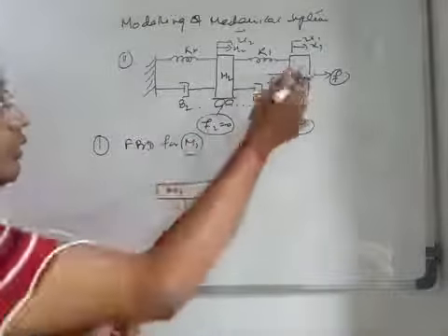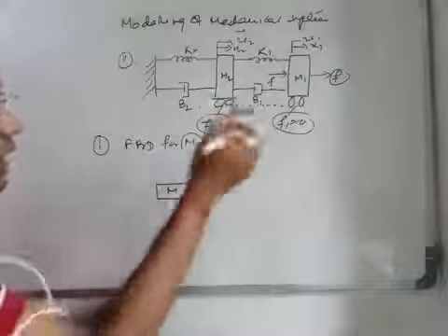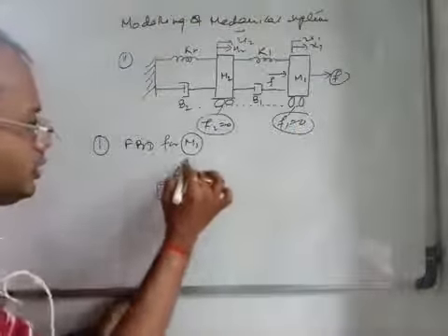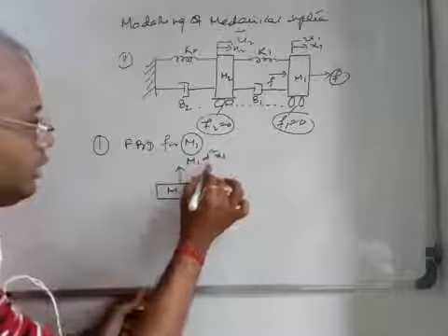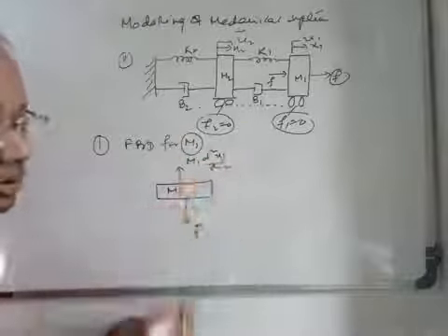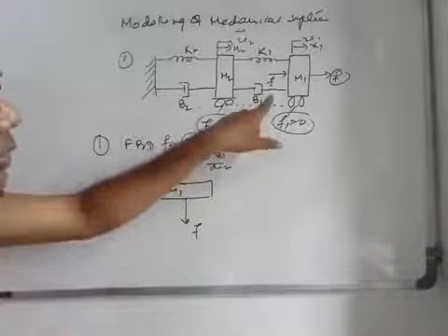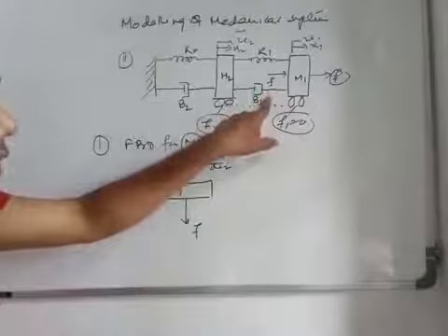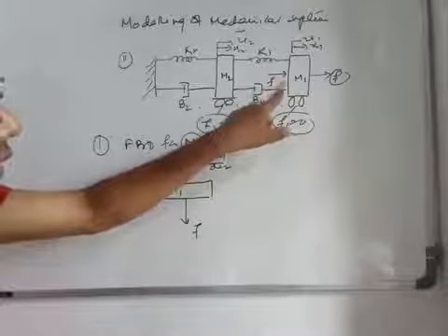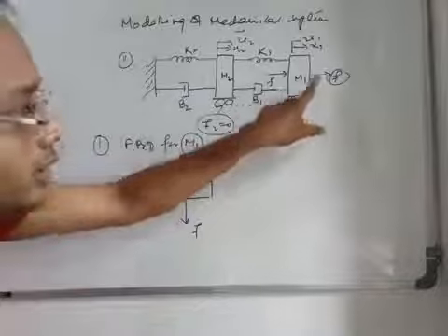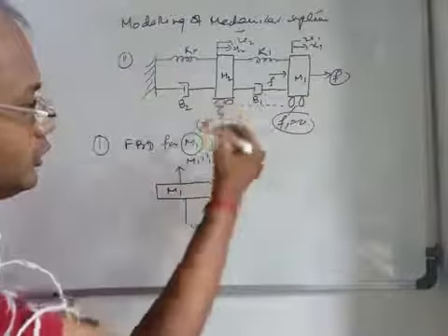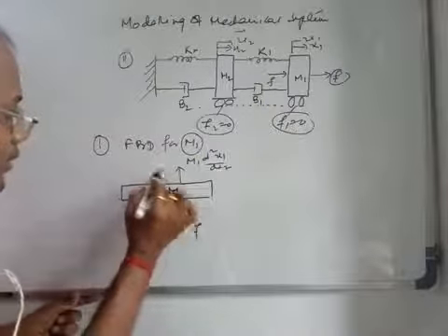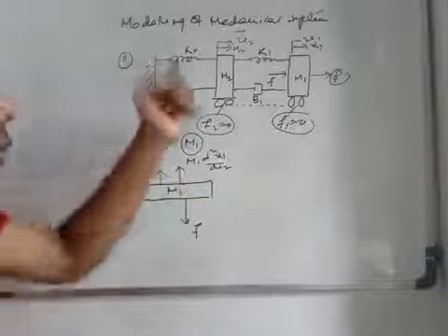So we have considered this outward force F, and corresponding to that, the displacement is x1. So the inertial force, m1 d2x1/dt2, will act in the outward direction, no problem. Now see, b1 is the viscous damping coefficient. The force that comes into the picture will oppose the motion of m1, definitely, right? So there will be another force which will oppose the motion of this mass m1.